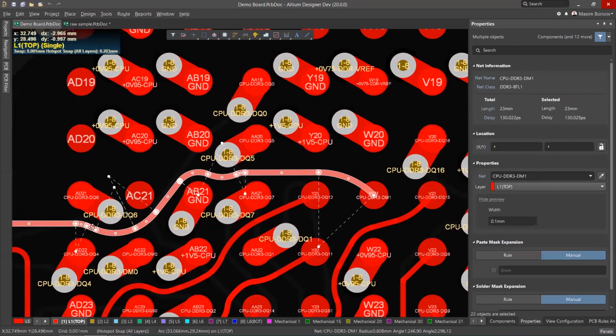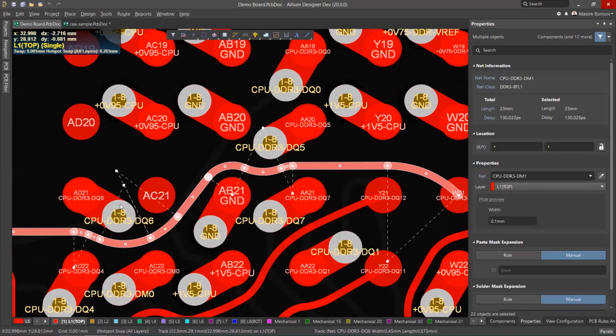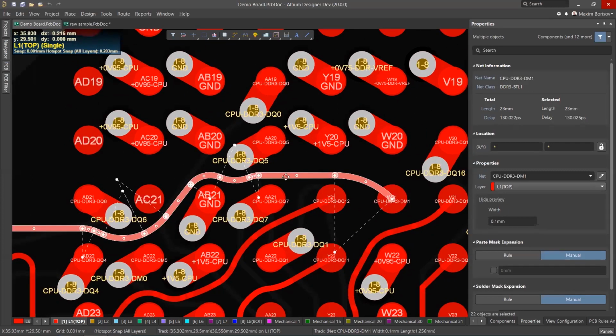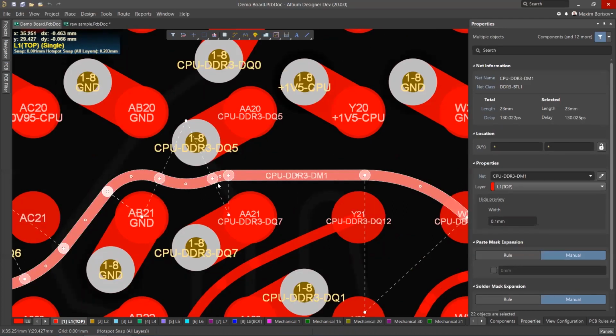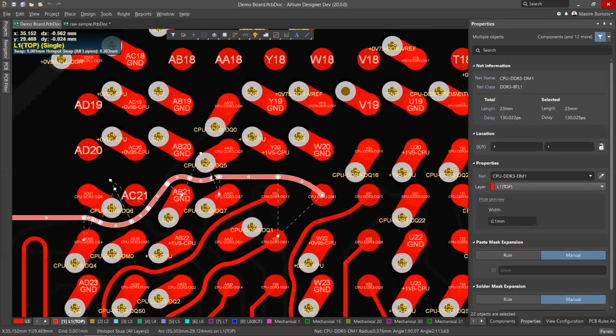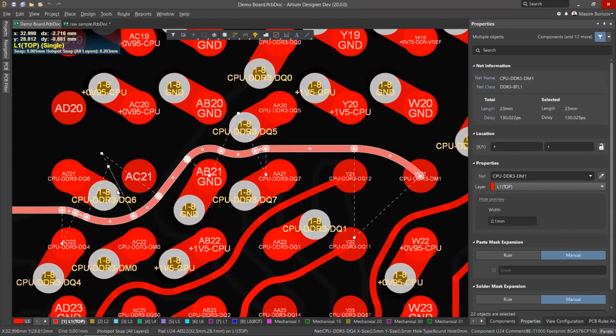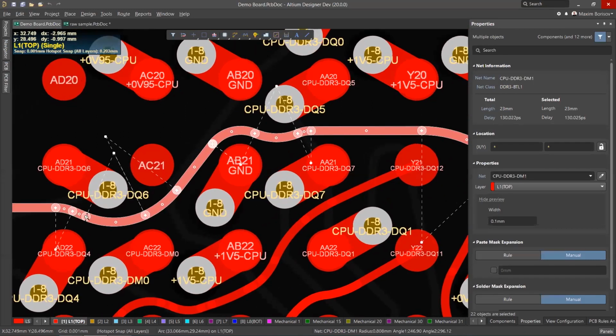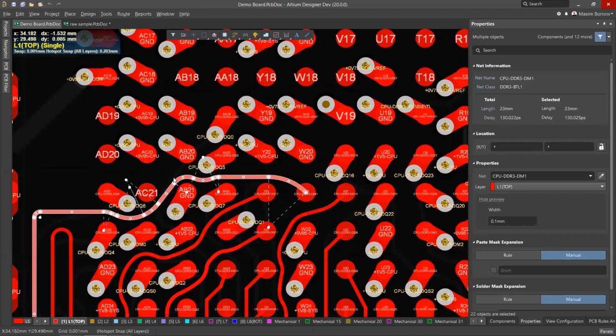You need to be extremely precise when moving the cursor, and extremely precise to make something that looks like tangent arcs, because it just can't handle the whole connection in terms of smoothness and efficient usage of the space, and of course the lack of DRC violations. It's very hard to avoid artifacts there.